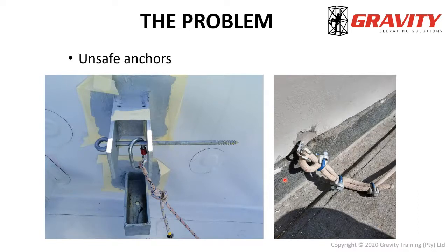And then on the right-hand side, you'll see the guy who used steel cable saddles on a kernmantle rope on a hanger, which is also in quite poor condition. Now, again, these types of DIY, self-improvised solutions to a problem are extremely dangerous, as this is in no way, shape or form approved by any manufacturer or allowed. So there's no guarantee of the strength of that anchor or the reliability of that anchor.